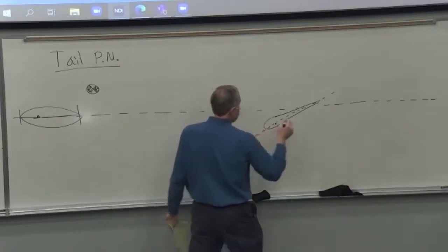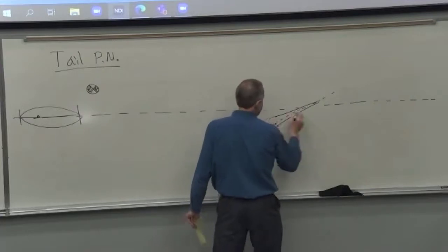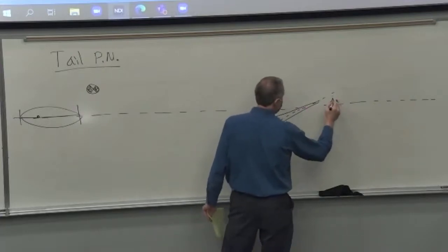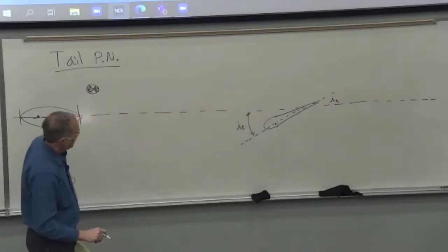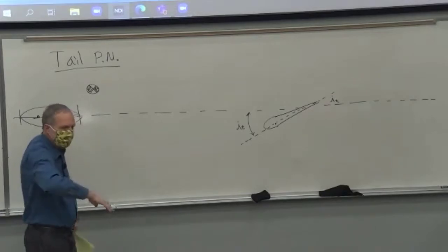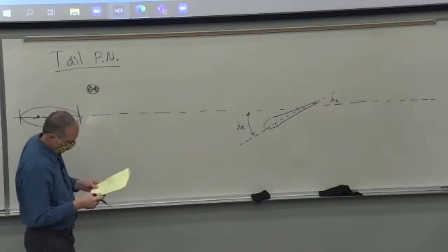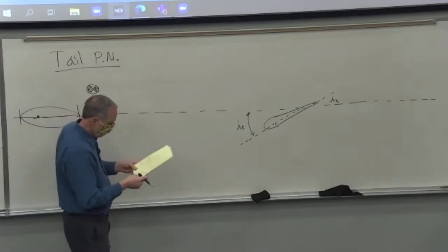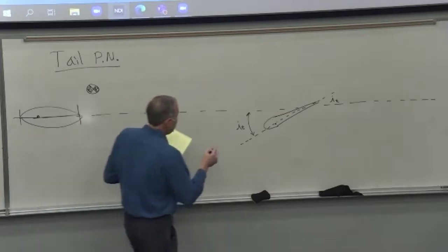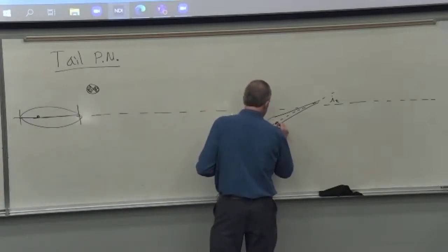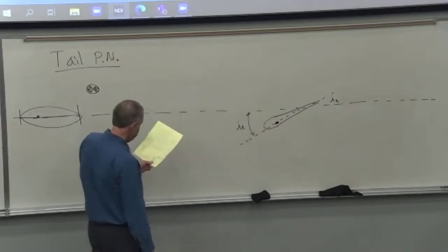And that angle is called i_T. Not for information technology, but it's the tail setting angle. It's just how much the tail is tilted down relative to the wing center line. Okay, so we've drawn the tail. And here's the aerodynamic center right here. So that's where the lift and the drag are going to act in the pure couple.